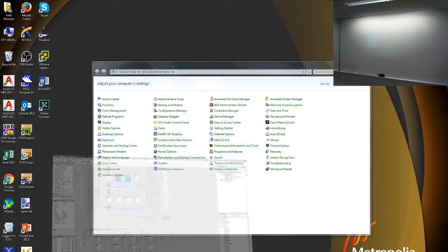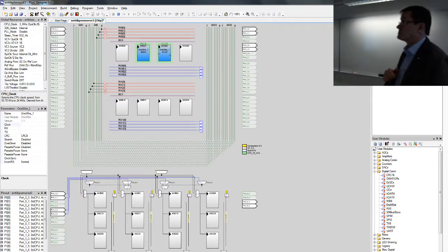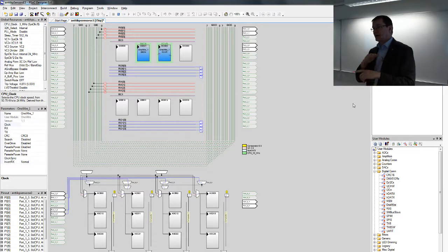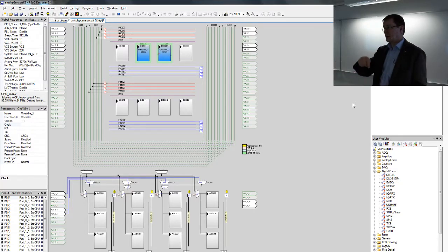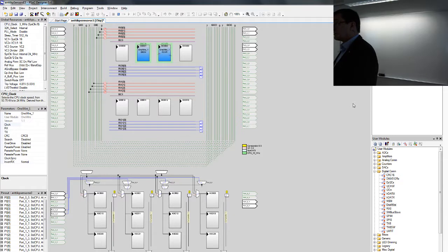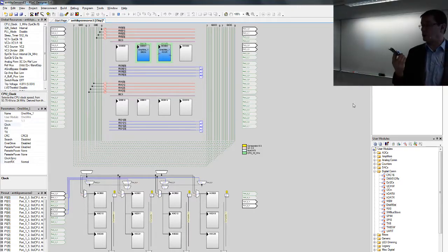Okay, back to business. Let me check that I have the correct view. So now we have that PSOC 5 board there just to bridge the data, but we are actually working on these PSOC 1 boards. So this design is for PSOC 1. The PSOC 5 development board uses a totally different tool chain. Only the programmer part is common, but otherwise it uses the PSoC Creator software for the development. This uses this PSoC Designer.